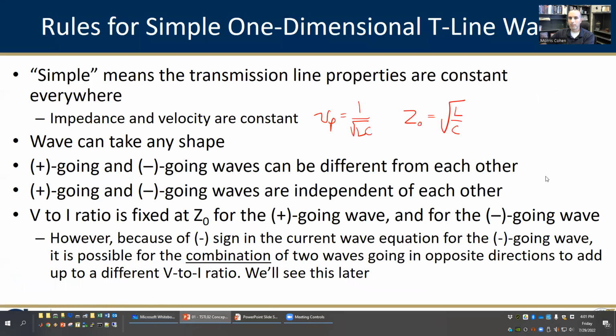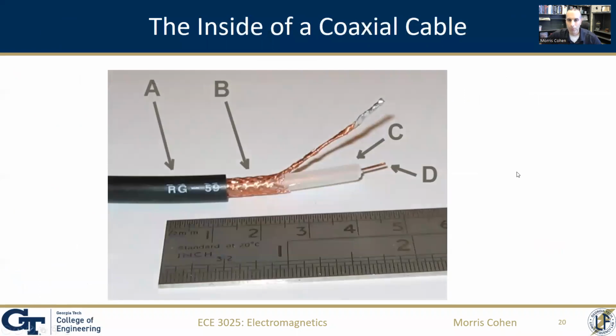Right, so if you take a look at the inside of a coaxial cable, for example, you can see a little more of the structure. The innermost part of the coaxial cable is a conductor. It's a thin wire, maybe consisting of little strands together, maybe one thick strand. This is very often copper, a pretty good conductor, although getting to be a little bit expensive these days, but that's what a lot of coaxial cables are made out of. And then around that inner conductor will be some insulating material with a dielectric constant, epsilon r. Around that, you'll have an outer conductor,